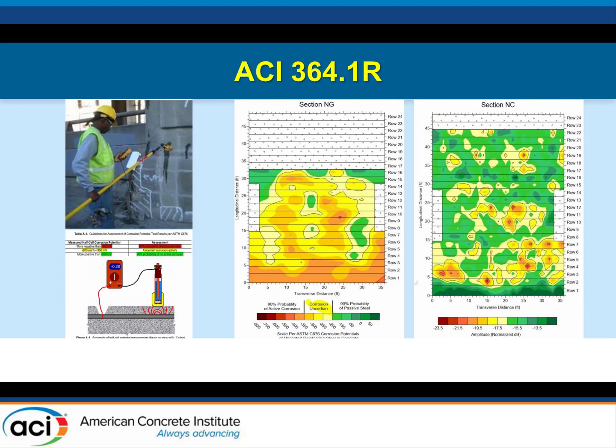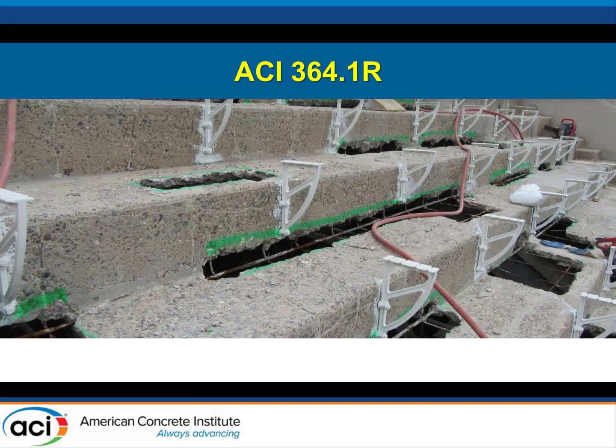The other thing we did was corrosion potential measurements, with copper sulfate tests. And again, we could scan the decks very accurately with this and produce maps. So we were able to come up with zones and translate them into what we thought were pretty reliably good concrete repair quantities. And of course, at the end of the day, that's what it looks like, right? There was a lot of concrete that came out, but the technology really helped us out on the quantities. I think it was tremendous for us.